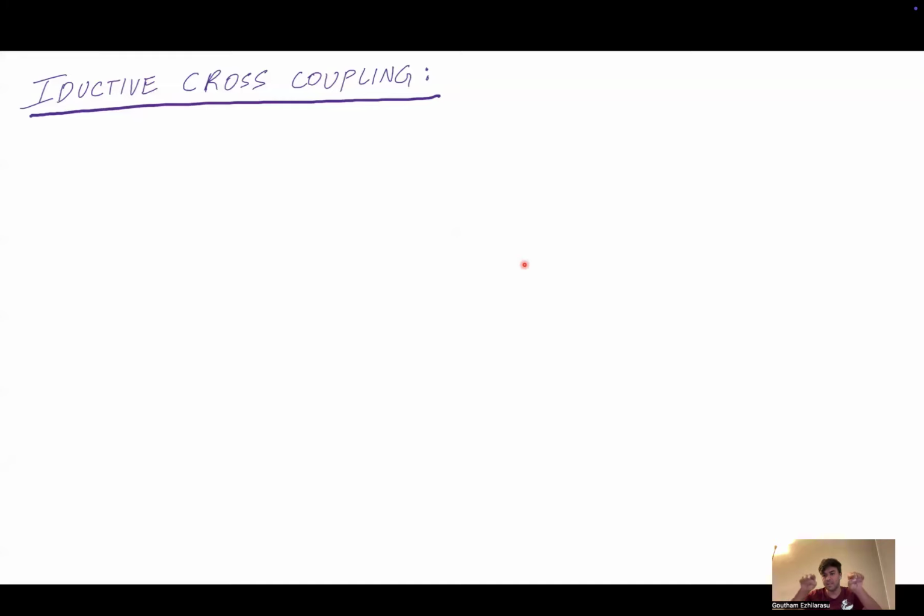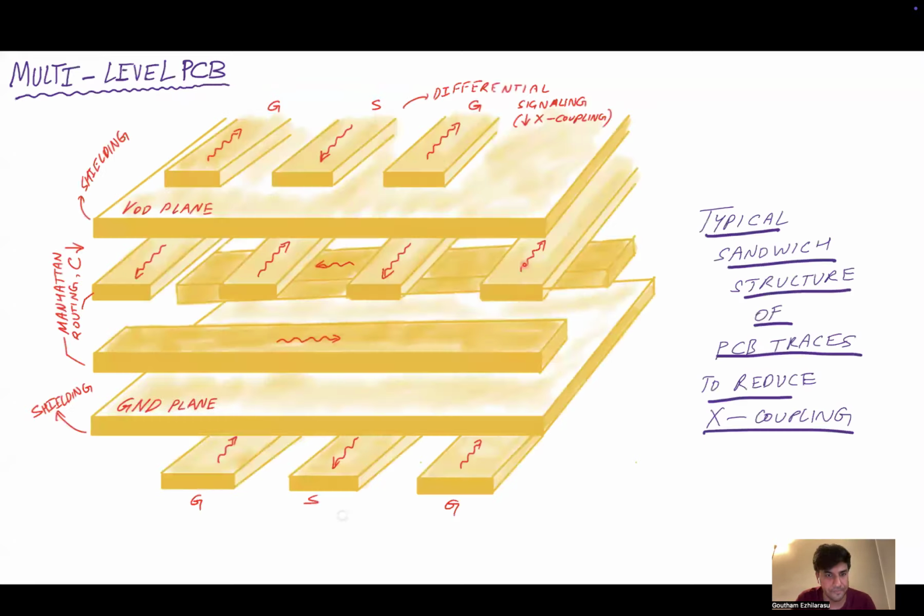And the amount of that induction from one conductor to the other depends on the mutual inductance between the two conductors, which again depends on how close the conductors are placed to each other, right? The magnetic property doesn't really matter because generally you don't want to put magnetic materials around these conductors, so it's just mu naught. But depending on how close the conductors are, as well as the frequency, this mutual inductance can be quite significant and has to be considered when designing these interconnects for signal integrity.